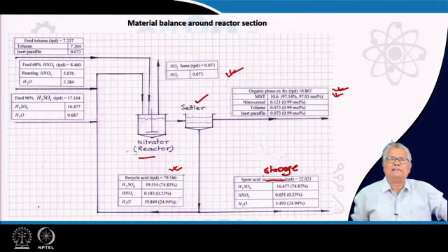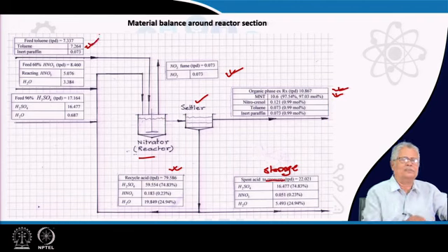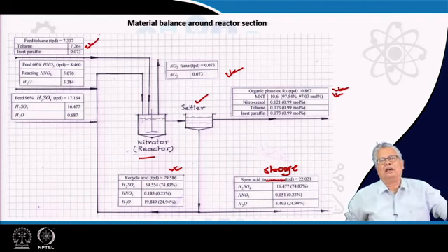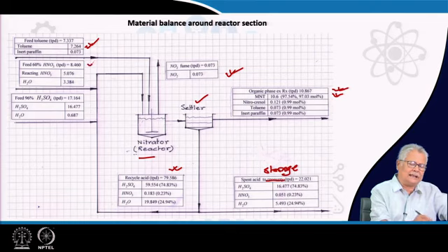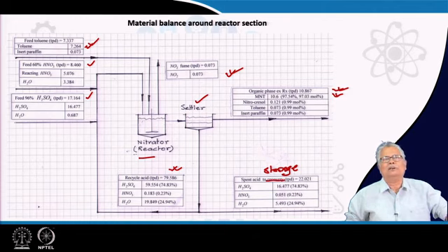If you look at the capacity of the toluene which is going to come in, it is roughly about 7.26, which is this amount. So, you will have every day at least one tank lorry of 10 meter cube coming in. If you look at the nitric acid and the sulfuric acid, which totally amount to about 25-26 tons, this will require about 3 tank lorries to be decanted every day.